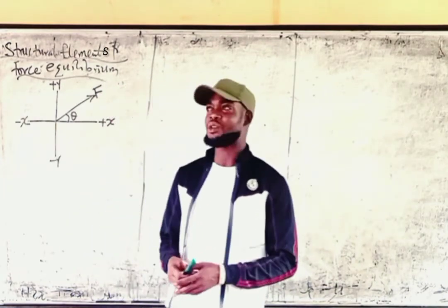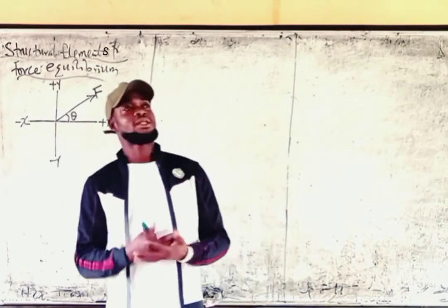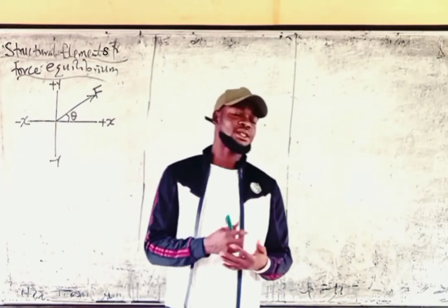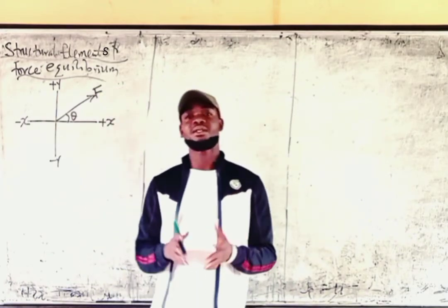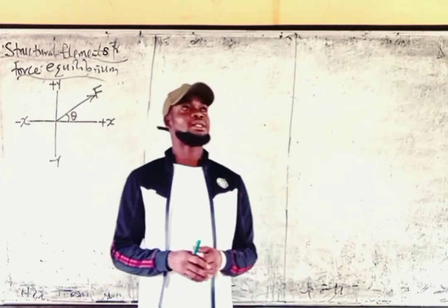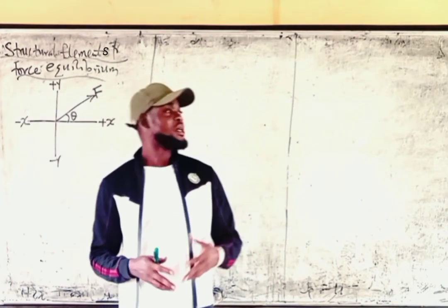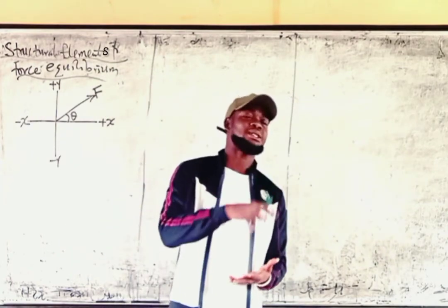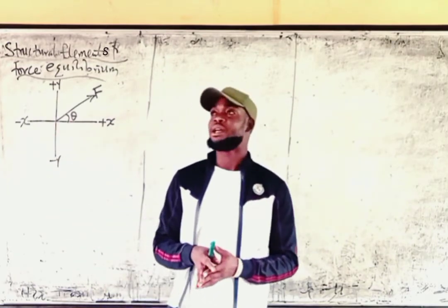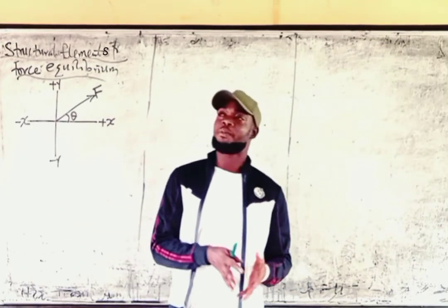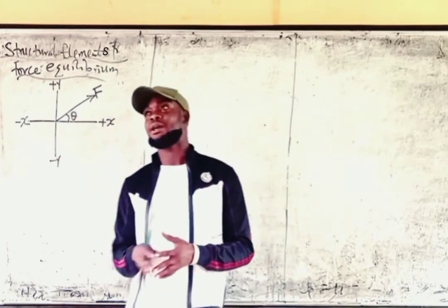Now, how do you use the resolution of forces? Resolution of forces is the act of splitting forces into its components. And what is the meaning of a component of a force? It is the amount of a force going in a particular direction. For a plane, a Cartesian coordinate of this nature, we have just two components, the x and y components.